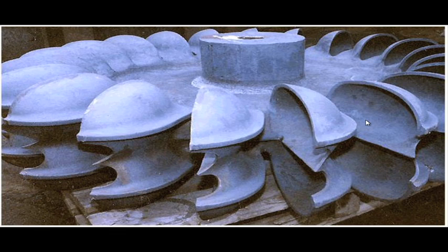This has been taken from a real Pelton turbine or Pelton wheel that operates in hydraulic power stations. You see, this is the shaft, here it is mounted, this is the large disc, and this is the spoon-shaped bucket. This is the splitter. So, water strikes here and it enters here and goes out like that. So, it is divided equally in two halves.